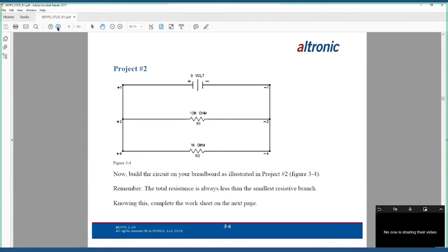But you say, well, let me check the resistance again. And all of a sudden you get this crazy number that makes no sense, but it's not an open circuit either. So this could be what's at play. Is there something else in that circuit, the overall wiring harness or the skid wiring going out to the device, that's throwing you off? And if it's wired parallel, there's one of your answers. That's one of the reasons why I like this exercise so much. And it's a challenge for me every time too, believe it or not.